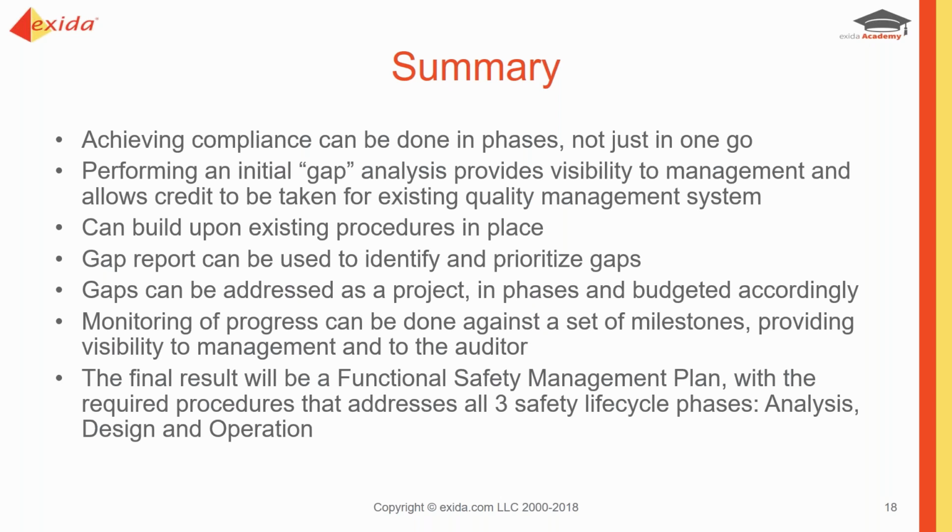So competency is very important, and the whole point of functional safety management, if those of you that have been on my course before or heard previous webinars, I always talk about the 3 Ps for managing systematic failures. Functional safety management is all about managing systematic failures. And the 3 Ps associated with systematic, of course, are our personnel. Are they properly trained and competent to do what they're doing? The second one is processes and procedures.